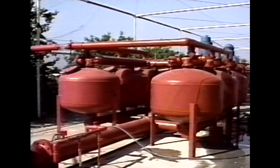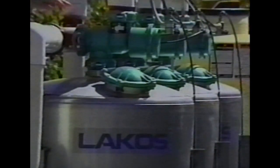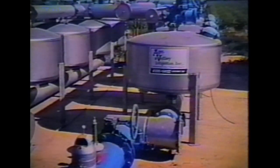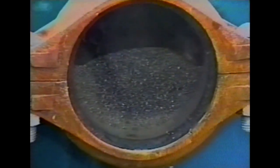Media tanks, also known as sand media filters, are pressure tanks filled with some type of sand-sized particles. They are the most popular form of filtration for drip and microirrigation for situations of a high dirt load of organic and/or inorganic material. The depth of the media provides a three-dimensional screening-like process that has much more debris storage capability than screens.